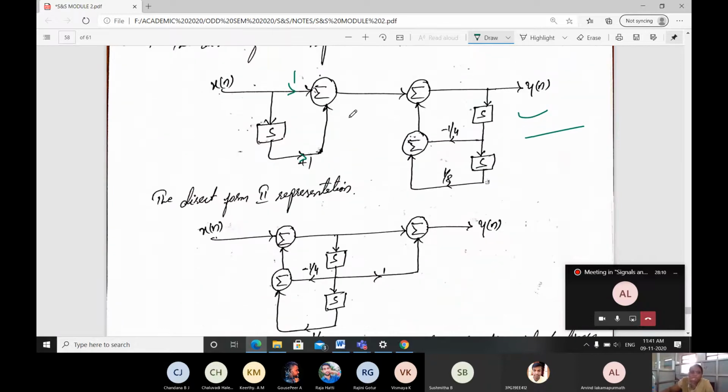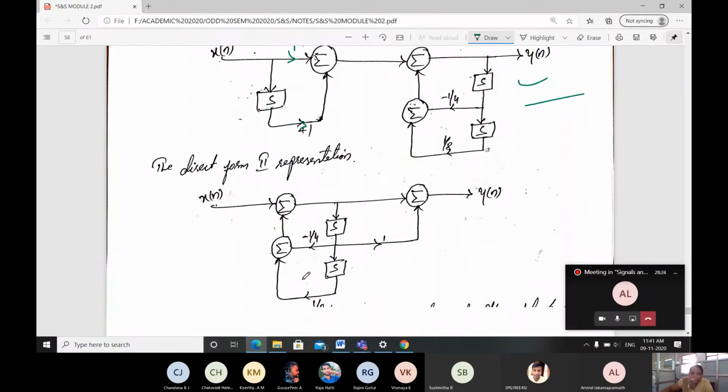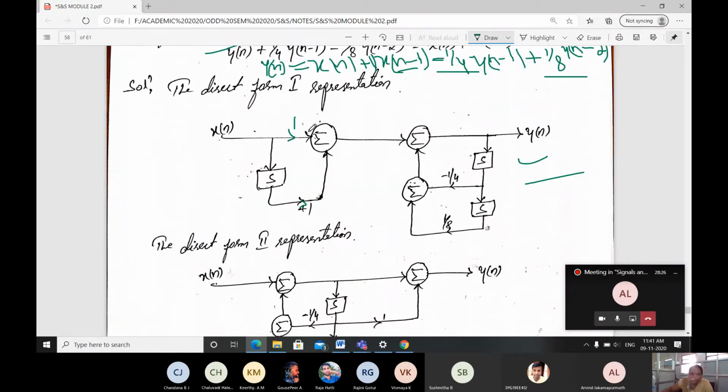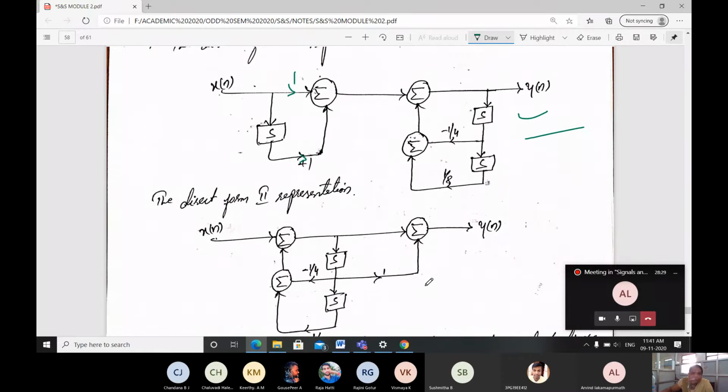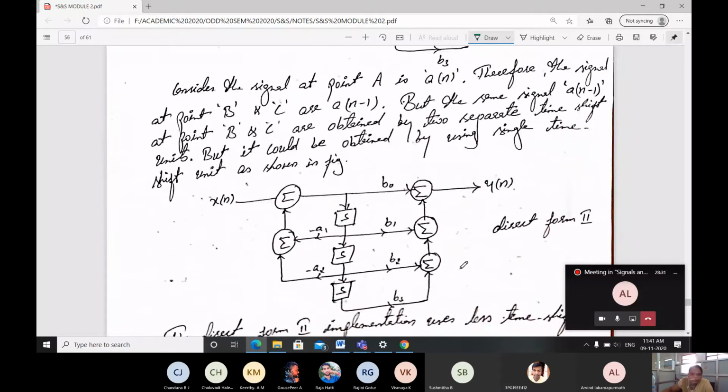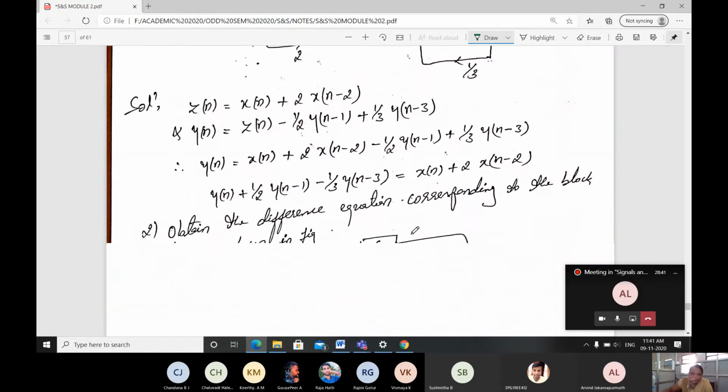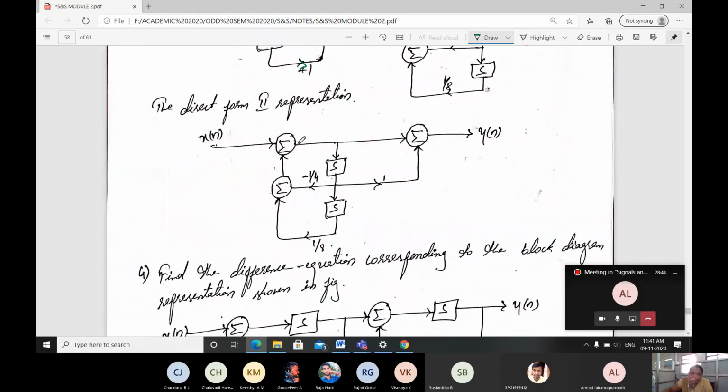In the same way, direct form 2. What is direct form 2? It is replacing of these terms. First we will be writing here as b0 b1 b2, here a0 a1 a2, but here we will be writing as a0 a1, then this b0 value. Okay, if I go for the direct form 2, here minus a1, minus a2, a0 is not there. Okay, minus a1 a2, b0 b1 b2 b3. Same thing here it is writing.